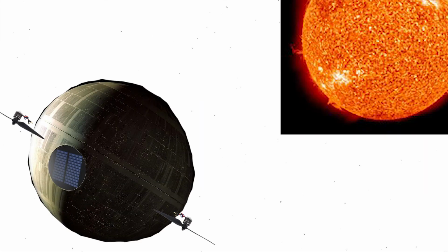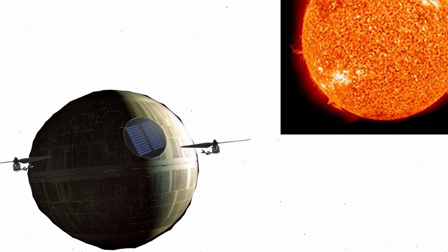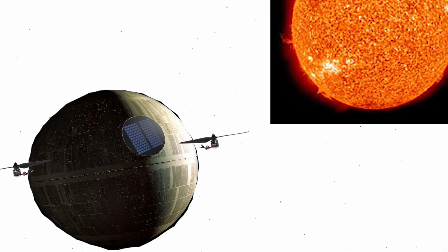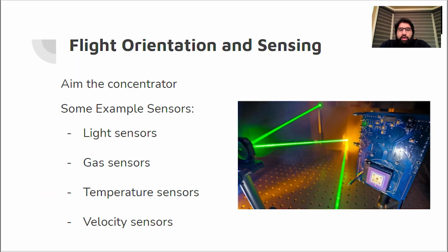In order to generate power, the device must be pointed at the sun. The direction of the sun will be determined with an array of light sensors. A control system will send instructions to thrusters, which will be used to aim the craft. A variety of sensors will be on board to collect data on desired variables, like atmospheric composition and other physical properties. Some calculations involved for this system include the development and tuning of a control system for aiming the device, efficiency and performance analysis of different orientation methods, and power consumption and reliability of sensors and systems.